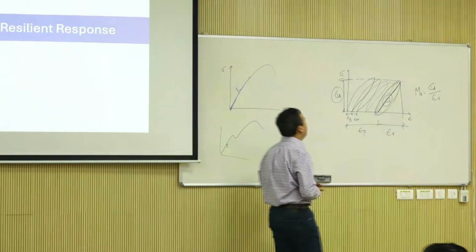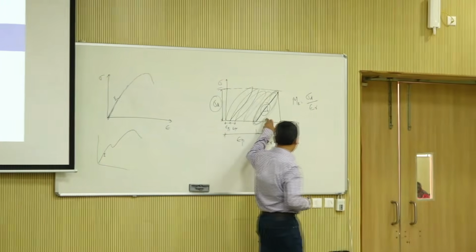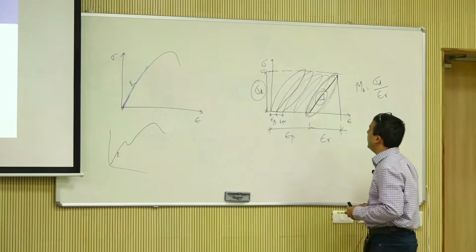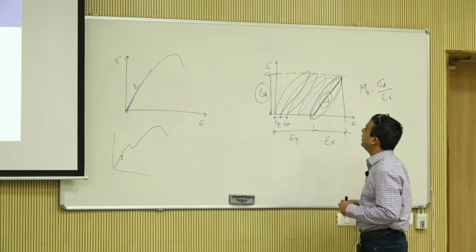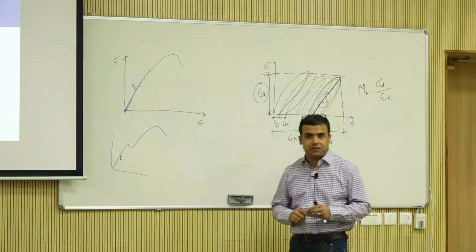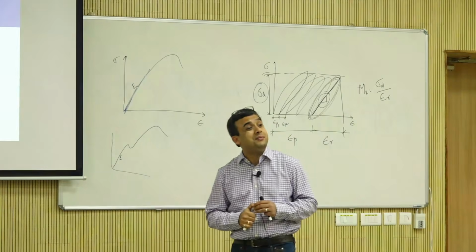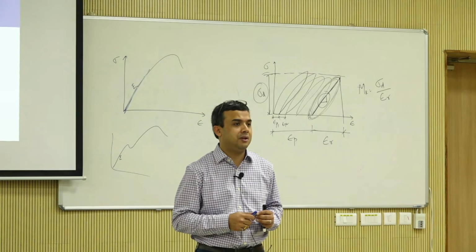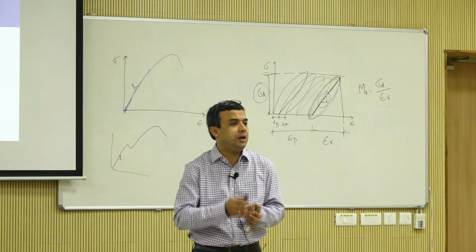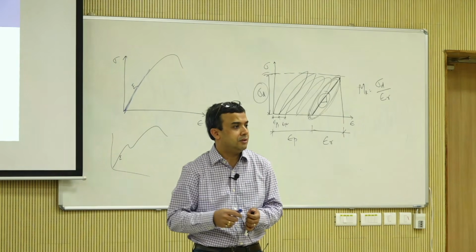Viscoelastic, I don't know. It doesn't have to be viscoelastic. It will have some information. There is the elastoplastic, but even steel is elastoplastic as well. Beyond the yield point, it's going to have a plastic behavior.